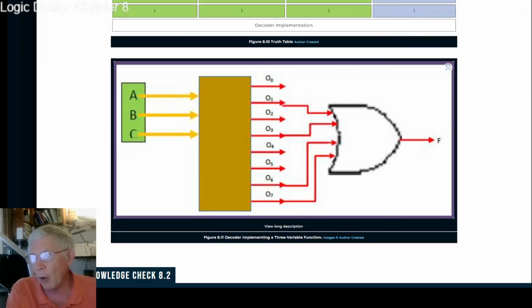If you want to have them all off, then you have to take the chip enable and disable the chip so that none of these are active. The other lines are probably zeros, unless your chip enable is off, and then they'd be floating, essentially disconnected.